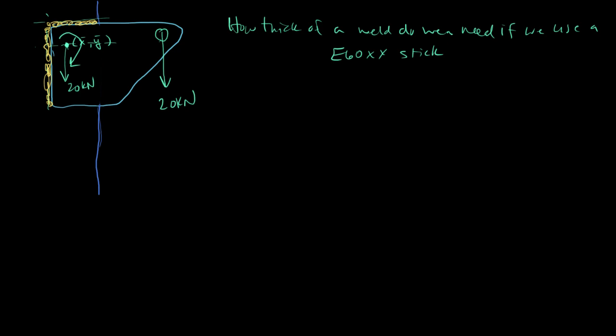So to find the centroid X hat position, we can just use the discretized formula for finding the centroid for each area. It's the sum of the areas times the distance x to that area over the sum of areas, sum of all the areas.